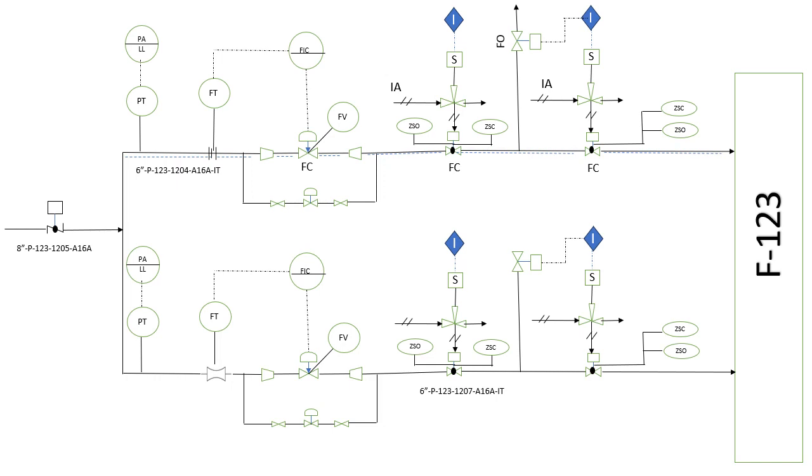One is natural gas and another line is off gas, and there are a pressure transmitter, a flow transmitter, and on-off valves, and it also shows you how this pressure transmitter is connected, where it is connected. This symbol indicates that it provides a display in the DCS, and it has an alarm, a low alarm.